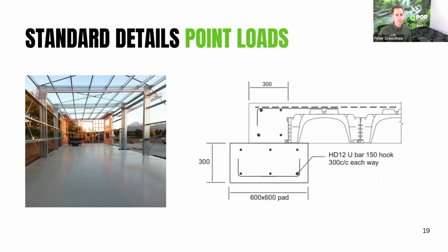The example image on the left was actually a rural barn. They were putting 8-ton trucks in there, so that was the demands. So that was a raft slab. I think they went slightly bigger ribs on that one, 150mm ribs, if I'm not mistaken. So it's all quite adaptable to different scenarios that engineers come up with around New Zealand and Australia.